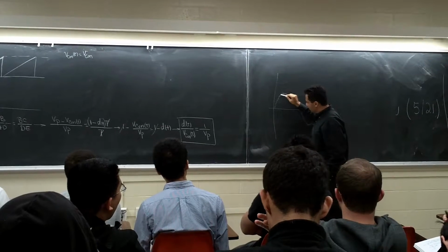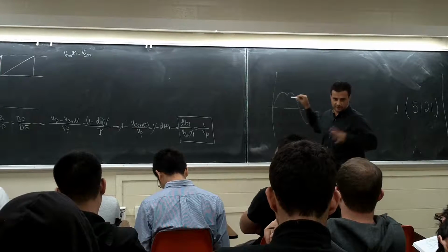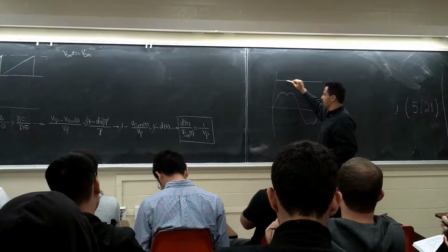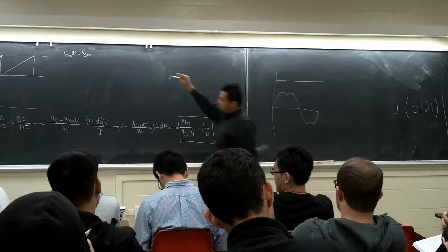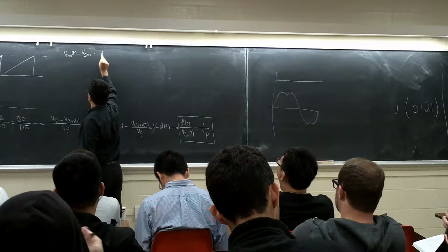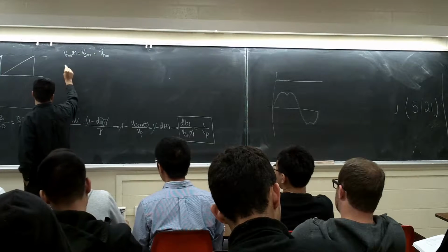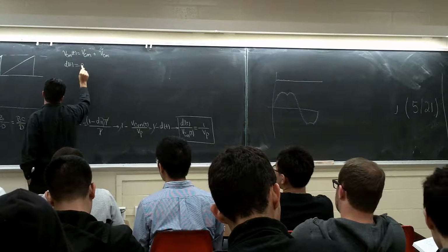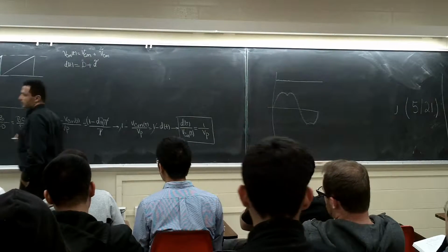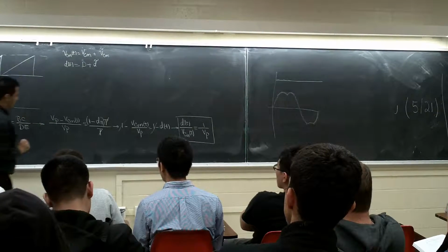But again here, for a DC to DC converter it is different. The values are DC. This is the AC system, right? For a DC to DC converter, we have something like this. So we write the control as the DC value plus V tilde control, right? And we know from the previous one, d(t) was D plus d tilde. So let's replace it in this transfer function.